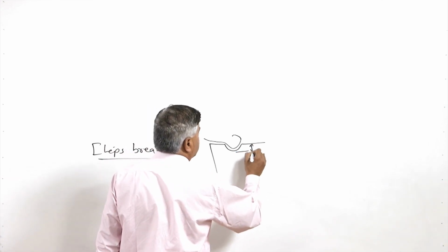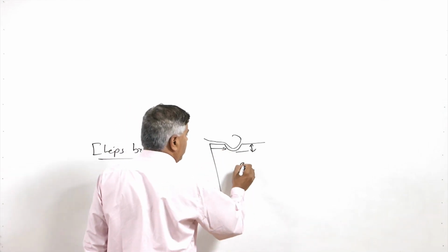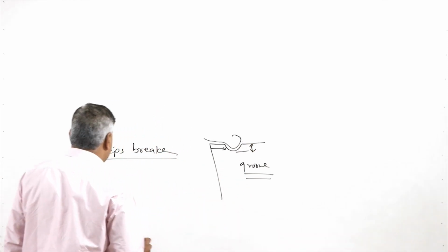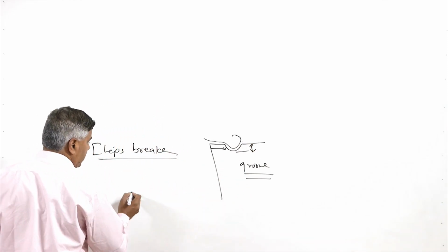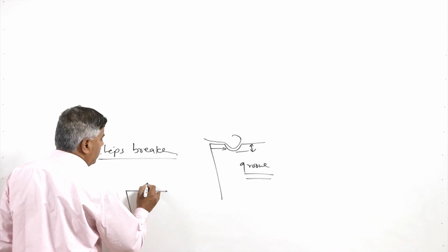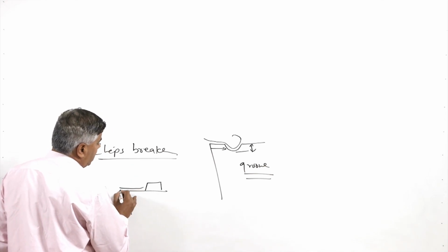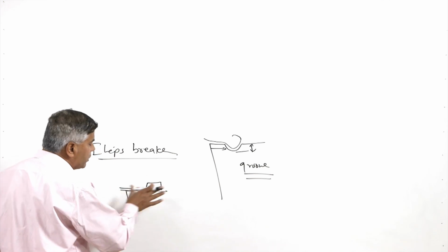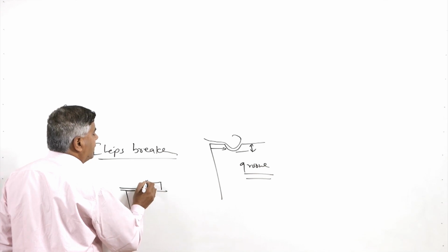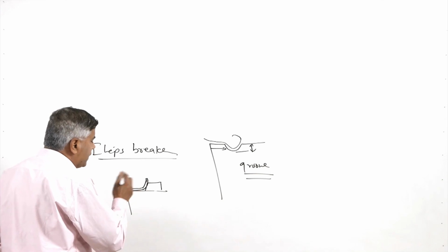The depth of this groove as well as its location away from the cutting edge are the two factors that govern the effectiveness of the groove type chip breaker. Another is the obstruction type chip breaker, wherein an obstruction is placed on the rake face of the tool in this way, so that after getting removed from the workpiece and moving across the face of the tool, the chip hits the breaker and gets curled, or its direction is changed, so that it is broken.